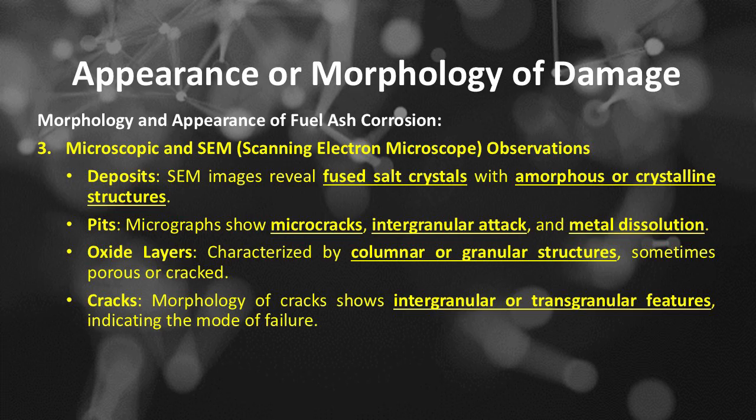Number 3, microscopic and SEM, scanning electron microscope, observations. Deposits: SEM images reveal fused salt crystals with amorphous or crystalline structures. Pits: micrographs show microcracks, intergranular attack, and metal dissolution. Oxide layers: characterized by columnar or granular structures, sometimes porous or cracked. Cracks: morphology of cracks shows intergranular or transgranular features, indicating the mode of failure.